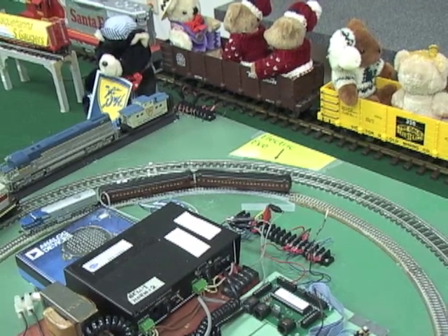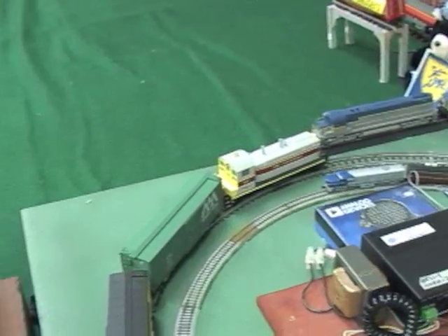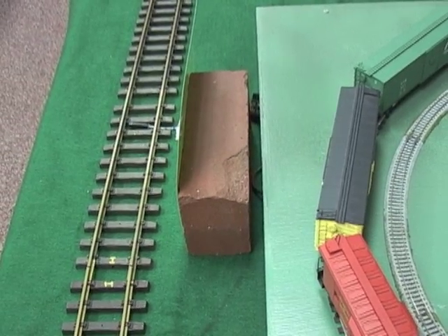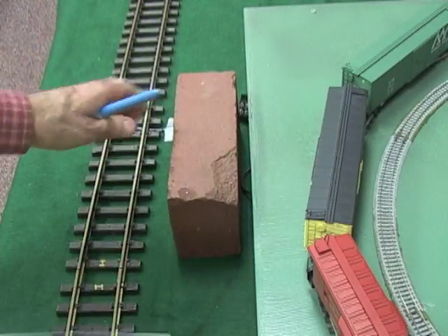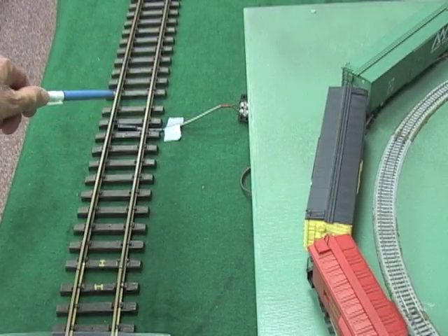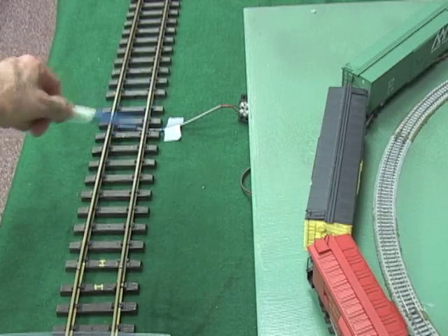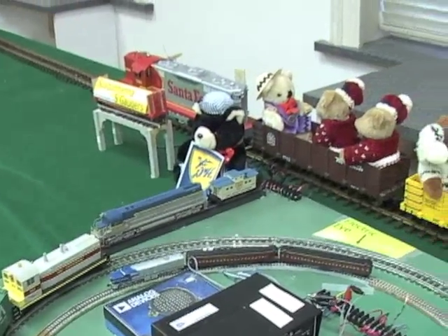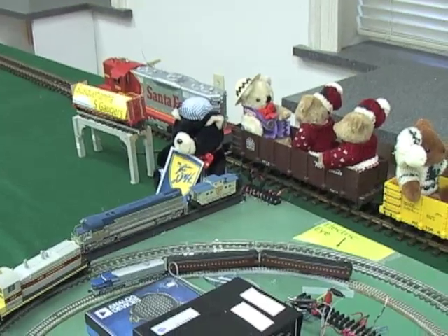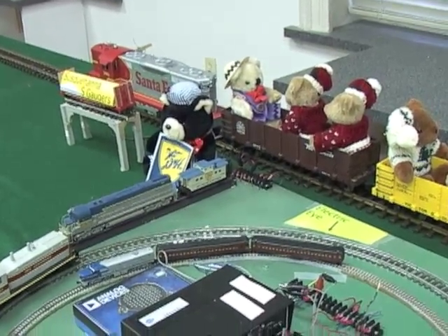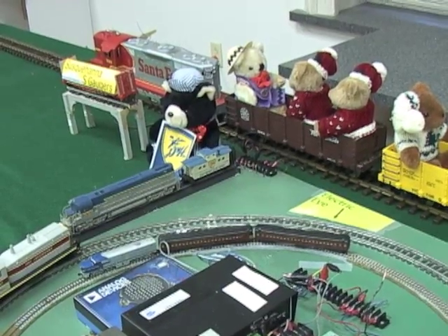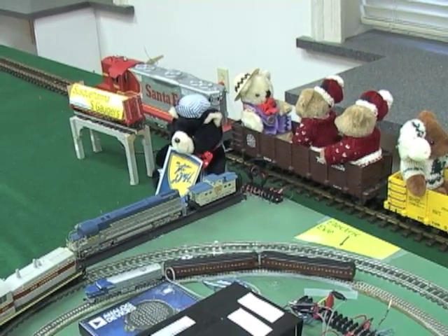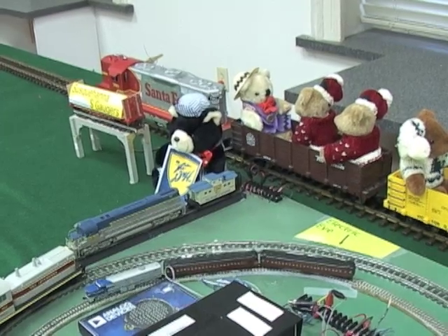The LargeScale train has reed switches in the track. Let me swing around to see those if we can. Right down here where the tape is, that's a reed switch, and there's another one over on the far side, just to the right of where the D&H bear is sitting. There's a reed switch in the track there underneath the gondola, and a magnet on the bottom of the loco on the LargeScale activates the reed switch, which tells the mini panel to slow the train down so it doesn't run off the end of the track.